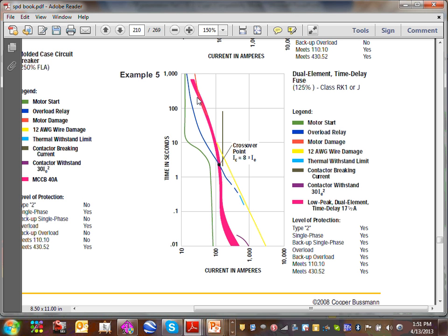Right in here, my damage curve is inside the fuse here. So you can argue the fuse opens before the smoke starts coming out of my circuit breaker here. I would like to see this curve move slightly to this side, on the damage curve side. That's supposed to give you the protection type 2 for all these things that could happen in your power system.